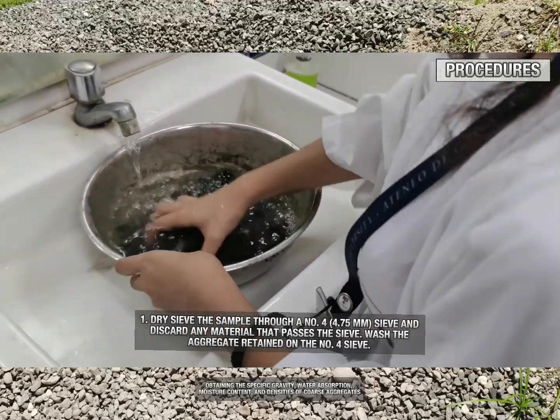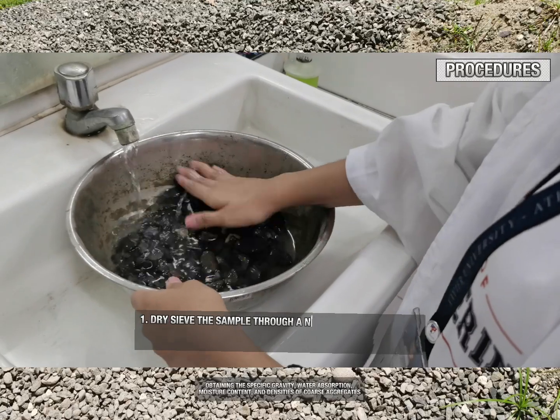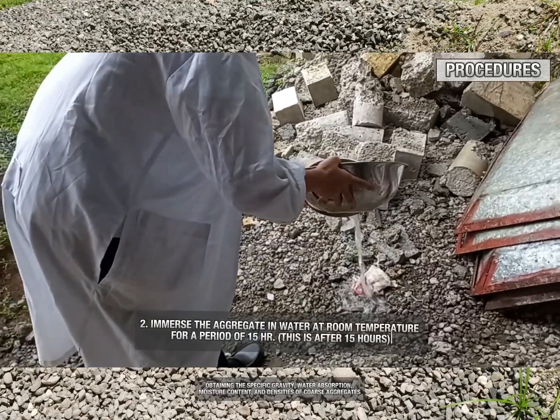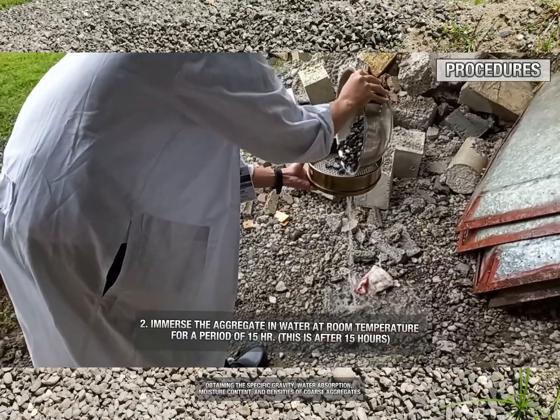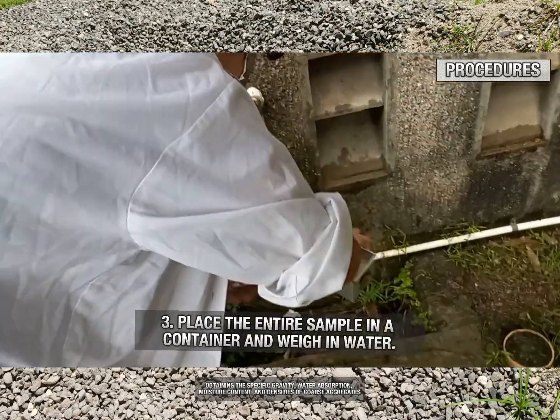Wash the aggregates retained on the sieve. Immerse the aggregate in water at room temperature for a period of 15 hours. Place the entire sample in a container and weigh in water.